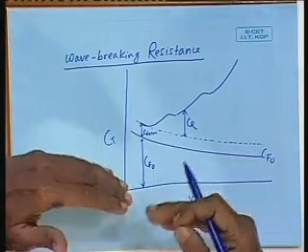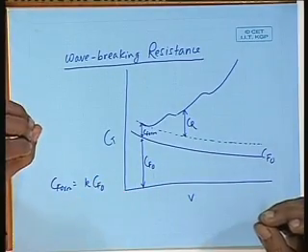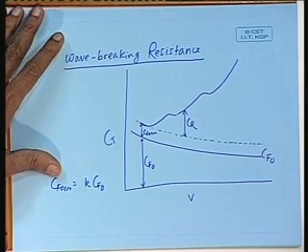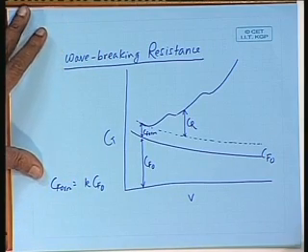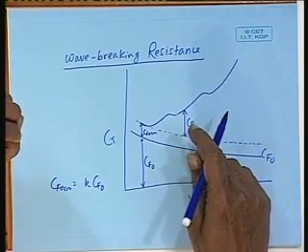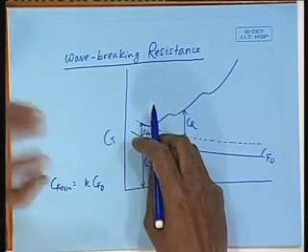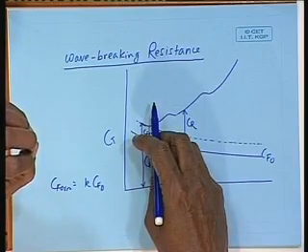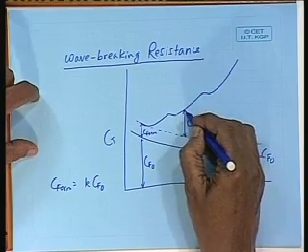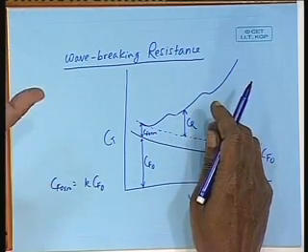But now we have said about other small components of resistance which may exist, like separation drag and like viscous pressure drag, etc. We are not very sure that this C form has some of these components. So, maybe they are in this CR, where the major component of CR is wave making resistance.